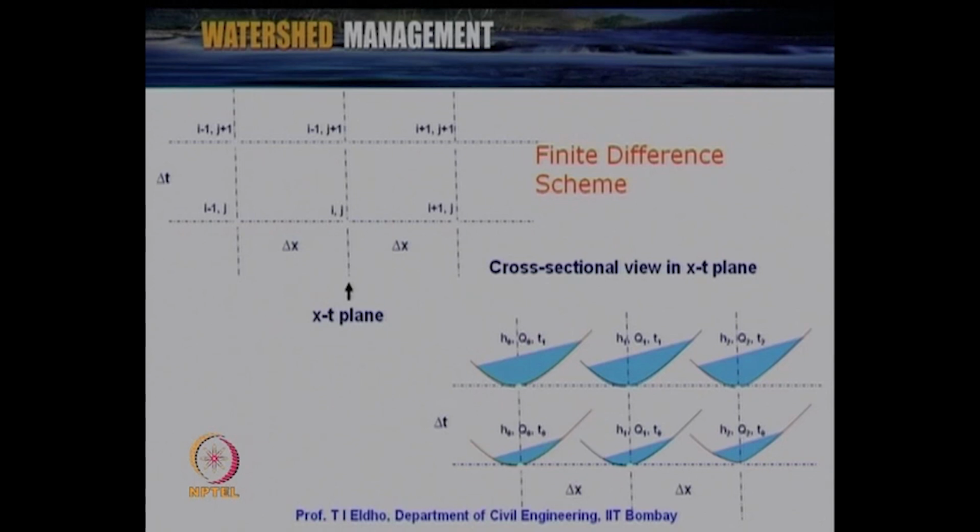Now, for example, if you are using the finite difference scheme while doing river or channel modeling, here is a one dimension model in the x direction, and t is the time. You can see that we can discretize like this with respect to the spatial x direction and time, and then correspondingly we can identify various terms like depth of flow or discharge at those particular grid points.